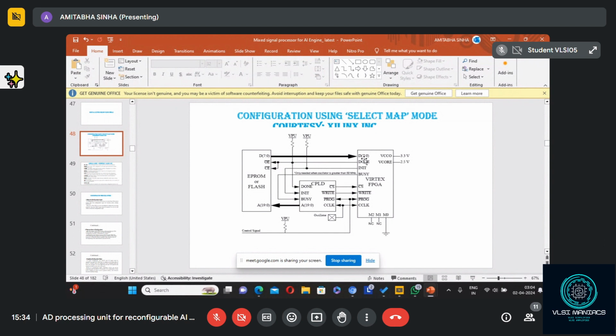After downloading, the down signal will initially go high. Once it has been stored in the FPGA, the down signal will again go low. That means it is ready for getting the next byte. By that time, the address has been incremented by 1, and the counter which holds the number of bytes to be transferred is decreased by 1.